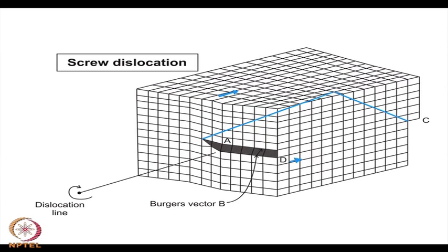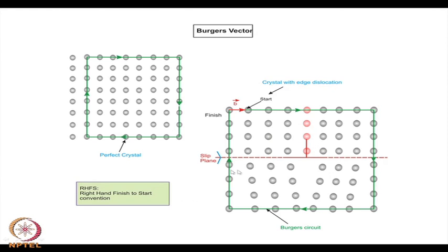Now, dislocation as per definition is at the boundary of a slipped and unslipped region, and here we have seen there is an extra edge. Extra edge is formed here, an extra plane which is the dislocation, and this particular dislocation is one variety of dislocation. There is a second variety of dislocation also, we will just discuss that.